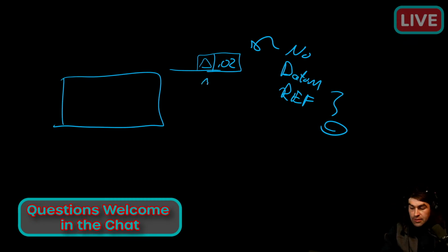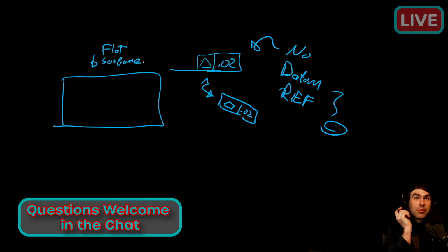It doesn't. If it's a flat surface, flatness and profile mean the same thing in this case. There is no difference. And in ASME, CMM should give you the same results because the profile isn't locating anything. Now, I can tell you, at least Calypso doesn't like this. It gets upset when you try to do it. It wants you to give it datums because it's programmed for ISO, I guess.